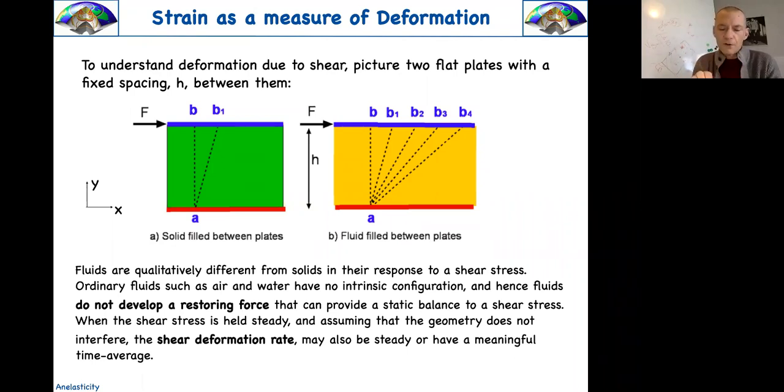Well, we have to move from a relatively simple concept of strain as a measure of deformation for real solids, Hookean solids, where you apply a shear stress, for example, and you have an immediate reaction, connected to mu, to the rigidity modulus, but then you're not making the system flow. If you remove it, it goes back to the origin. That's the essence of mu.